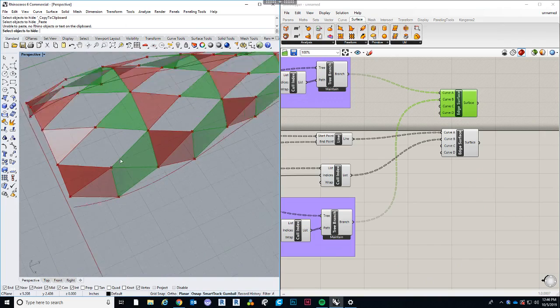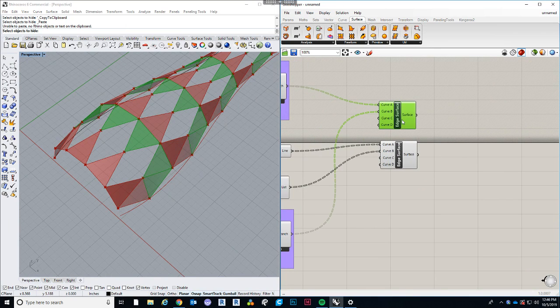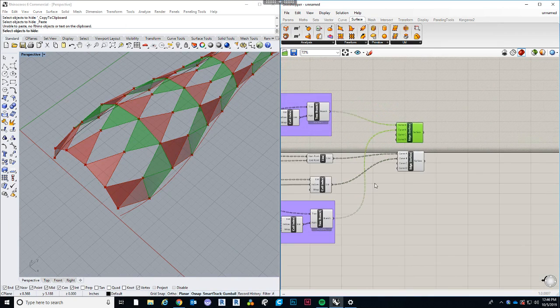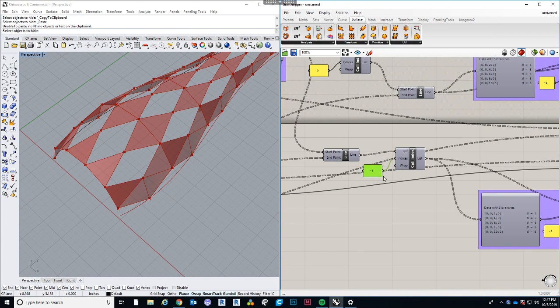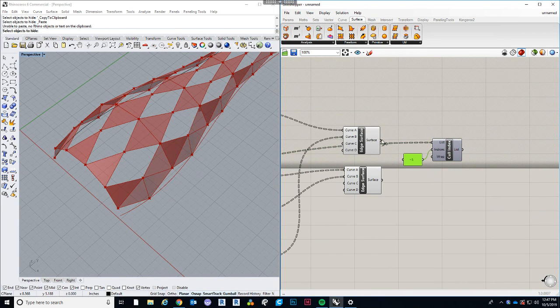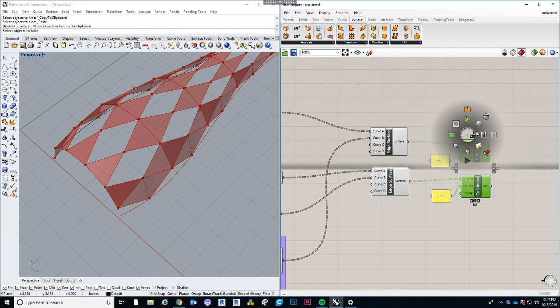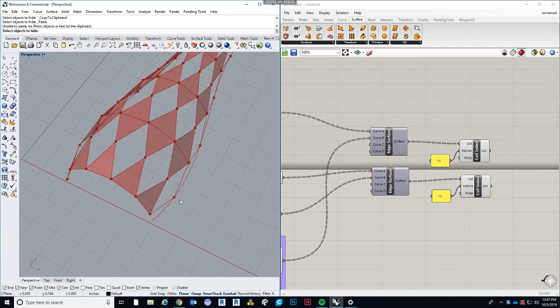It's creating recurrent surfaces back here, so we'll want to remove those first. Go back to one of our Cull patterns that removes the last item of the list, the one with the -1. Plug those in, copy and paste that down, and make sure to preview it again. Alright, now we've removed those.